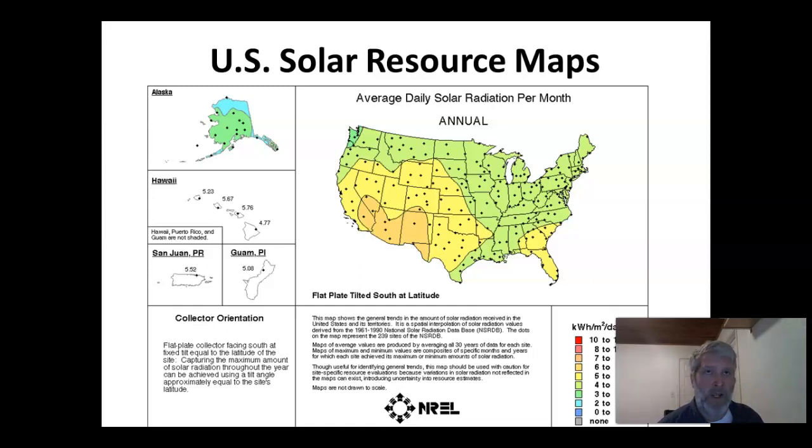So when we're doing a grid-tied system, why this is important is because we can pretty much just go off the average. We're going to get a credit based on net metering. So what we can do is we're going to overproduce during the summer. We're going to underproduce during the winter, but the summer's production, even though it's only 3 months, will actually make up for the winter's reduction. And so we'll be within a few dollars of what the credit is.